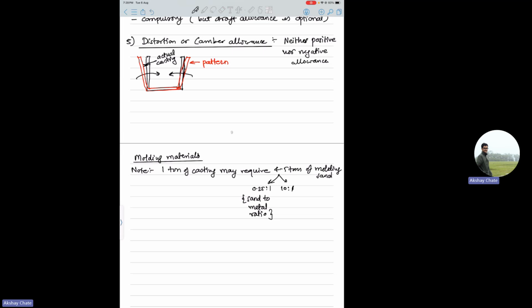And the most common type of sand is silica sand. You all must have seen this somewhere. Granules type of structure, and depending on the distribution of these granules, flowability, permeability, compactability, etc. depend. Its melting, or rather sintering, temperature is around 700 degrees Celsius. So it is a very good option for casting, because typically we don't go that high in temperature for metals to solidify. Melting points of metals or alloys are typically less than that, so we can use sand for making the casts, patterns, molds.